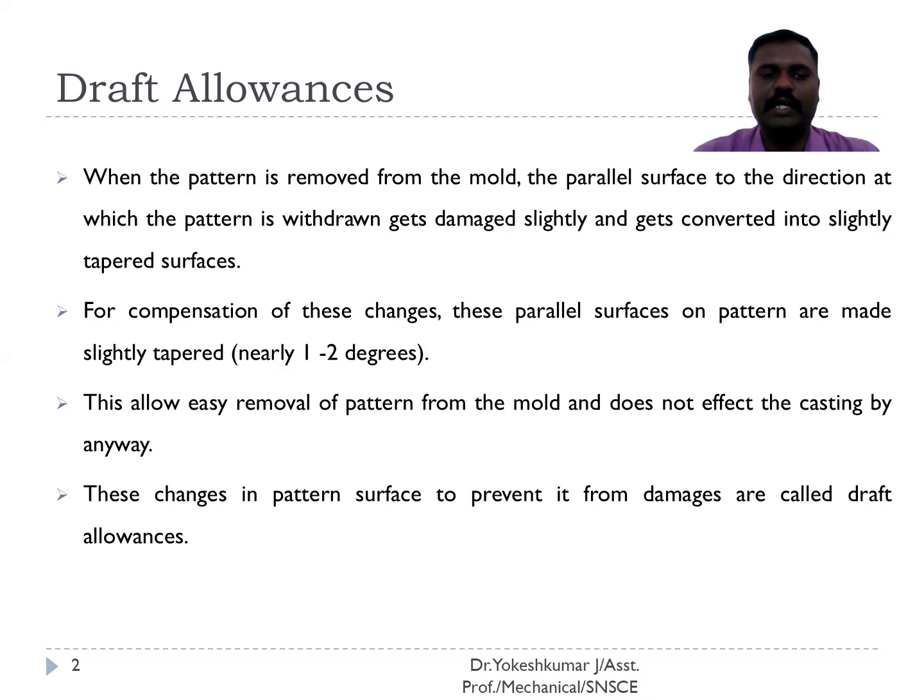This allows the pattern to be removed from the mold without affecting the dimensions. These changes in the pattern surface that prevent damage during removal from the mold are called draft allowance. This allowance is also called a withdrawal allowance.